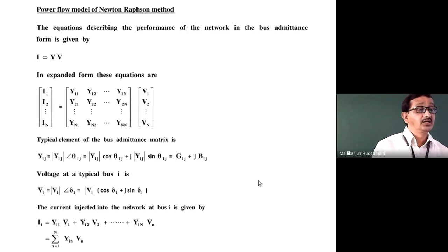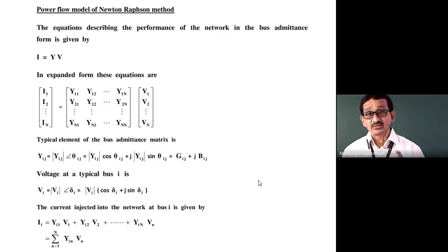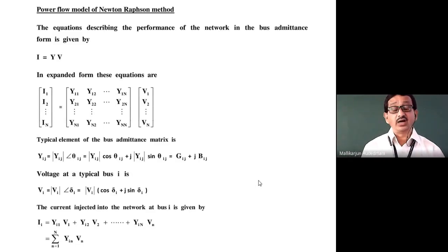Now what is this matrix's dimension? N cross n. It is the system admittance matrix representing the transmission mechanism, how the buses are interconnected to one another. Having n buses in the system, definitely I can connect a transmission element between bus 1 and 2, bus 1 and 3, 1 and 4, 1 and 6, 1 and 7, 10 and 11, 21 and 27, like that.